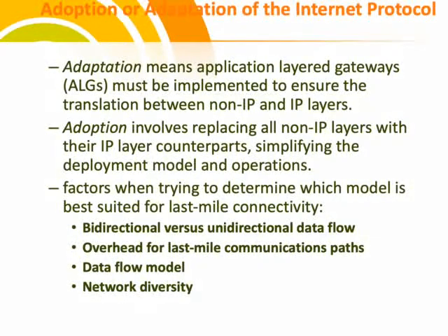What are those factors? First factor, bidirectional versus unidirectional data flow. Whether that particular temperature data should be bidirectional or unidirectional. In general, if you consider the temperature sensor as an example, it is a unidirectional data flow, because whenever we run our application, that is to monitor the temperature in the particular classroom, the only thing we are supposed to do is read the data. So the data should be sent only from the sensor towards the processing layer, or towards the viewer or the cloud, in only one direction. So there is no need for bidirectional.